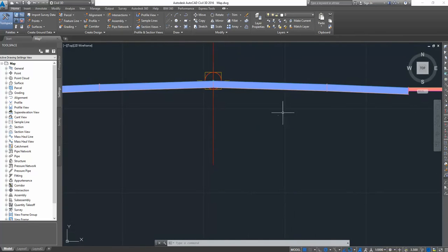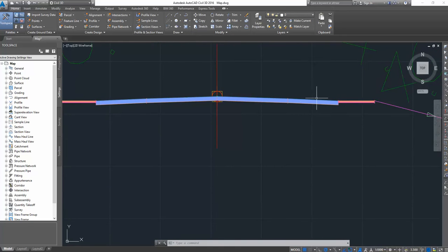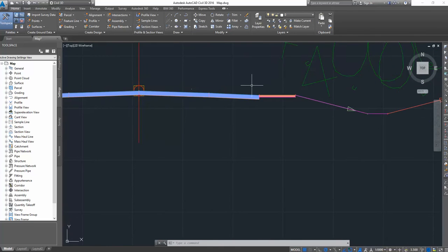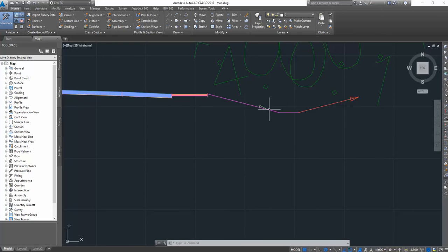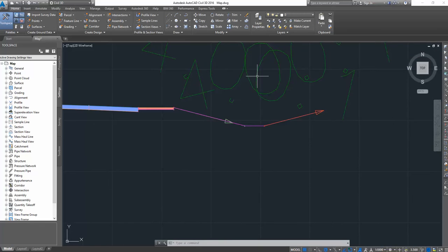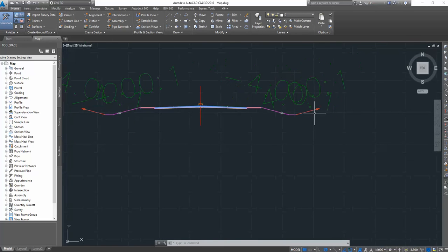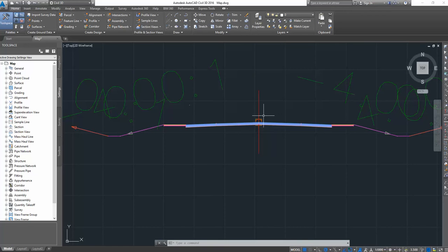The assembly is here. It has a lane width of 3.5 meters, a shoulder width of 2.5 meters, a pavement of 1.8 meters. Then it cuts down, so it goes down at a slope of 4:1, side for however long, and then up at a slope of 4:1 as well. So that's your assembly. That's your road cross section.